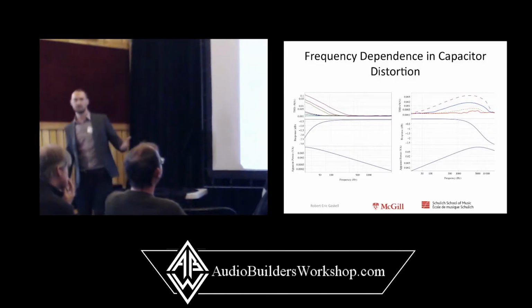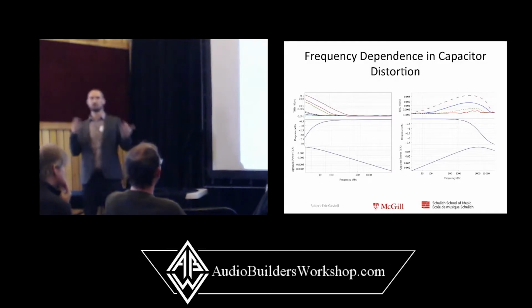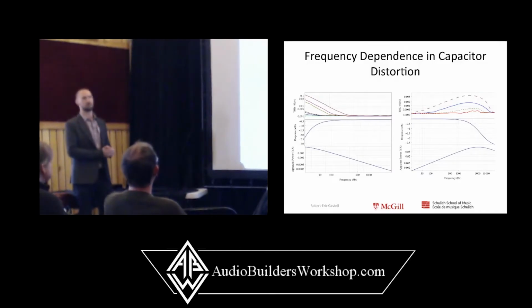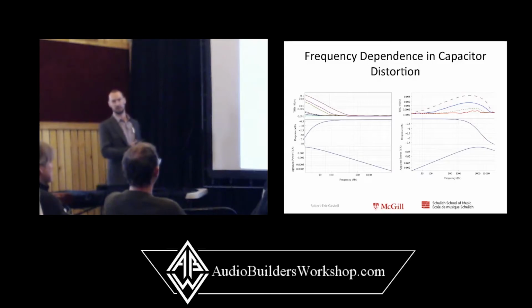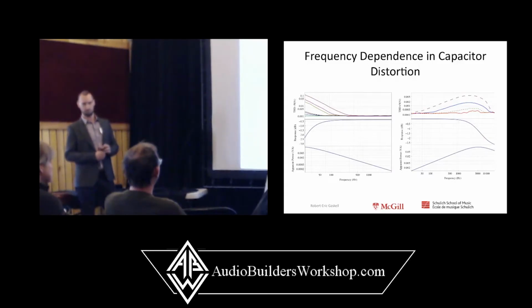So let's go to the next slide. Here is a high-pass filter, and we see that the harmonic distortion rises at low frequencies. But with the ear not being very sensitive to distortion at low frequencies, I wasn't able to have people hear the differences between electrolytics and tantalums.